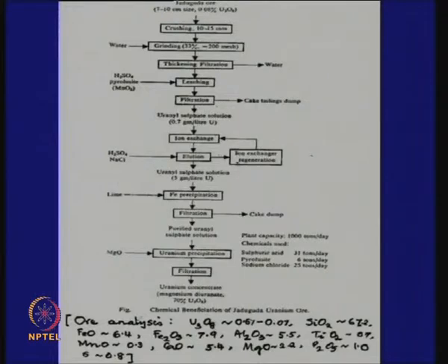In ion exchange, the resin is constantly regenerated, and after elution we get a solution where uranyl sulphate goes up to 5 grams per liter. Then we go through some chemistry steps. If we add lime, iron will be precipitated and separated out as a cake, leaving purified uranyl sulphate solution. Then by adding MgO, after filtration we will produce uranium concentrate, which will be 70% U3O8.